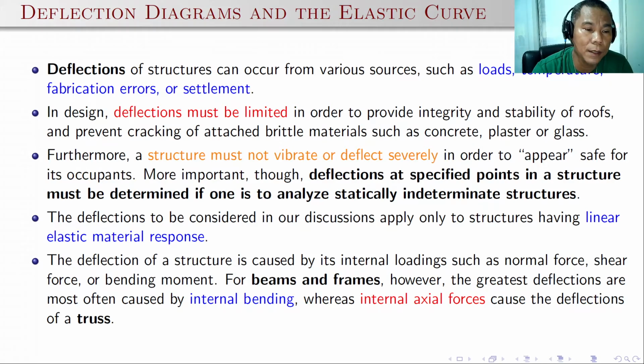The analysis of deflections for nonlinear response, that is beyond the elastic limit of the material, is beyond our discussion. So take note that linear elastic material response is that when you apply a load and then remove it, the material will go back to its original length. If you discuss what is beyond the elastic state, then that would be a different topic already.